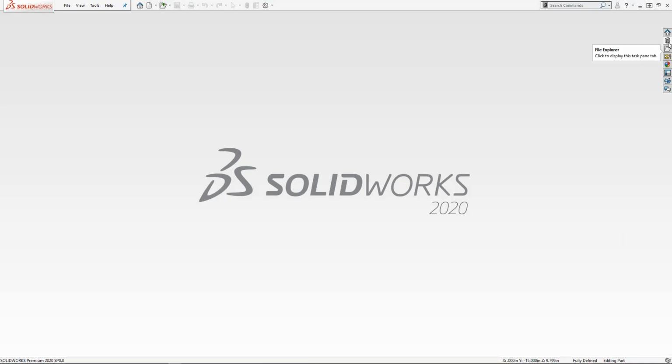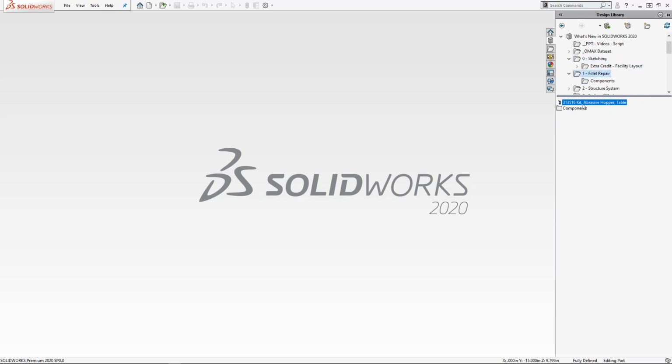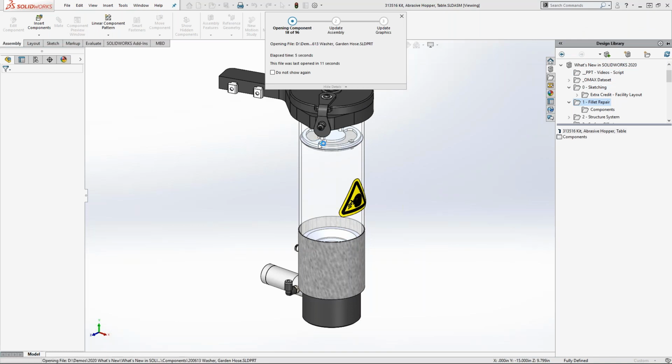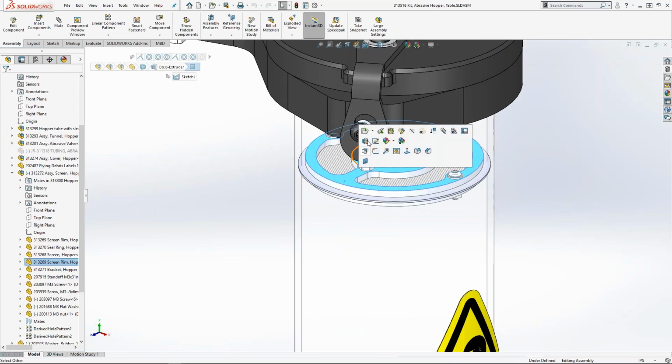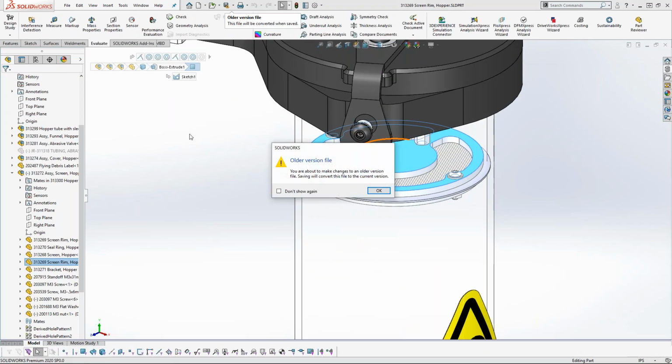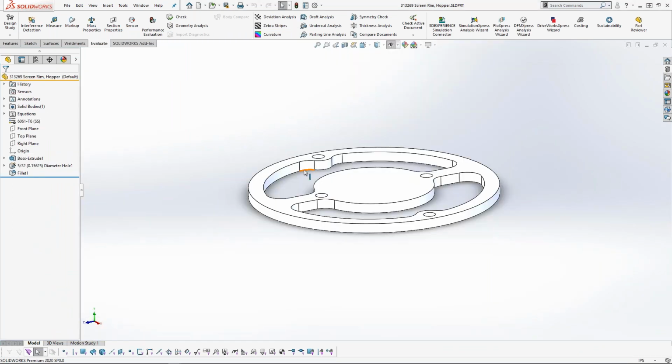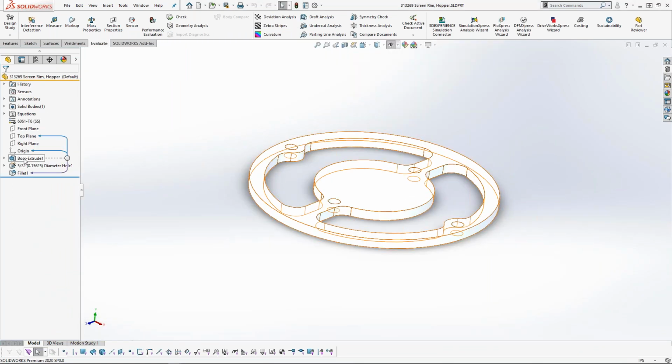So let's dive back into SOLIDWORKS, and I'm going to open up this component here. More specifically, I'm going to open up this one in the middle. So let's let this assembly load. Select this component, and we're going to open it. Now here we have different features. We have one that represents a boss extrude that is actually cutting out all of this contour. So it's cutting out these pockets as well as the perimeter. And we may want to change that.